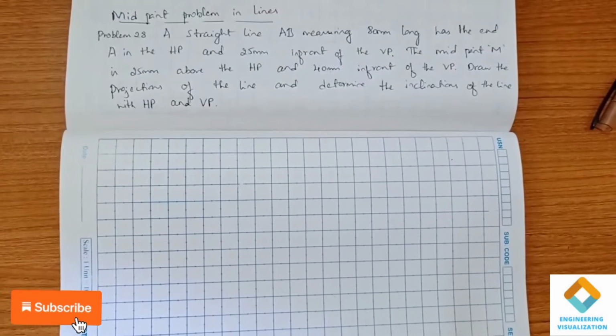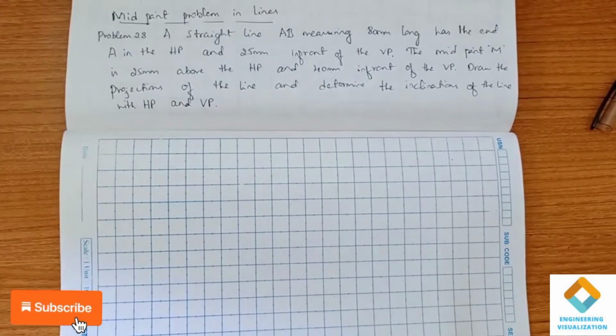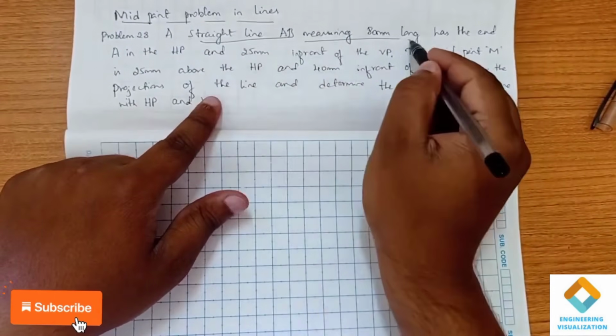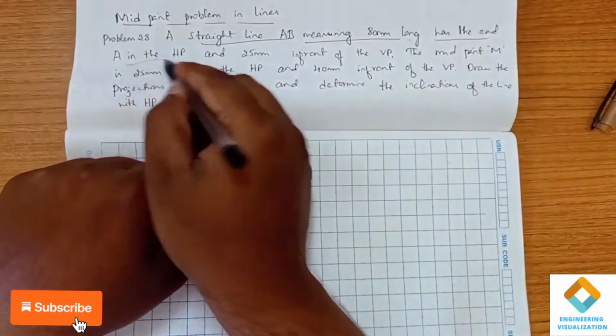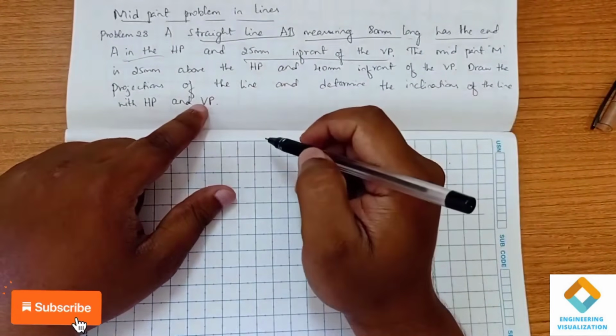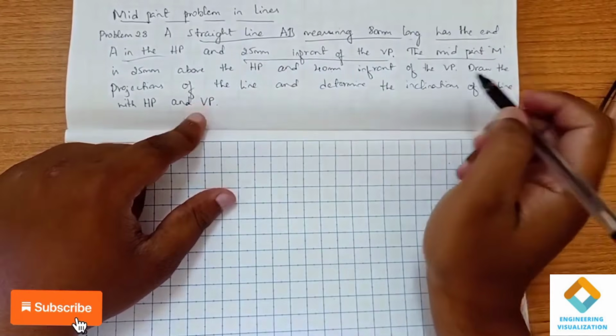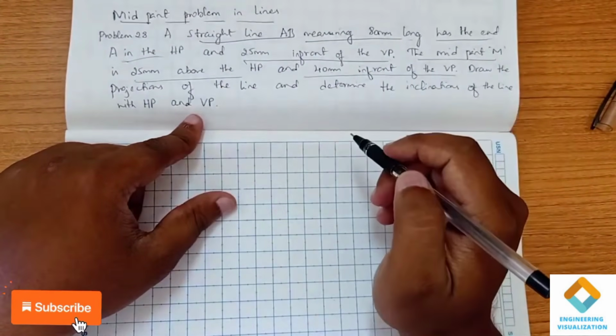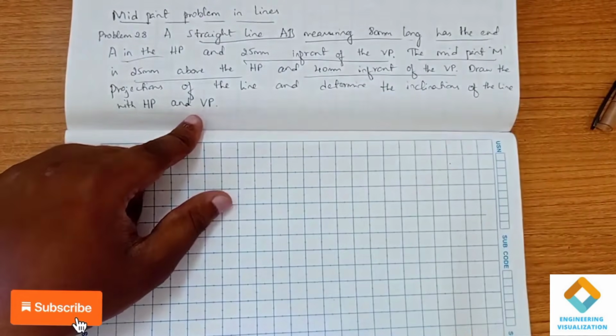Today we are going to do a midpoint problem in projection of line. Okay, so this is one of the important problems. Here in this problem, a straight line AB measuring 80 mm long has the end A in the HP and 25 mm in front of VP, and the midpoint M is 25 mm above HP and 40 mm in front of VP. So this is our problem.